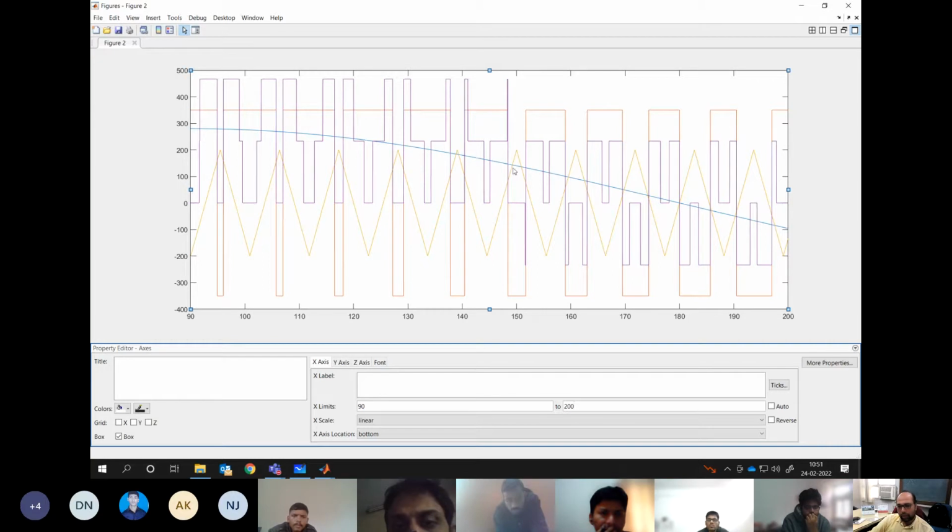And as you come down in the modulation index, lower values, somewhere you may see only VDC by 3 and 0, which is what we have seen in our case, right? So for lower value of modulation index or lower value of your, wherever you are doing analysis, if that corresponds to lower value of M, then you may not see all the voltage levels. It is only for the higher modulation index or close to the peak of the fundamental, you will see another voltage level coming up.